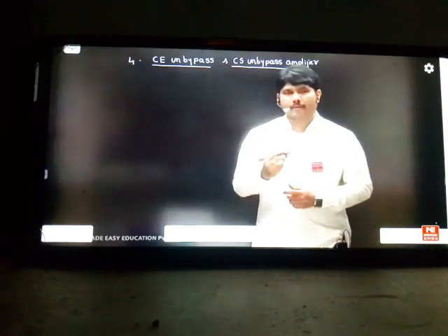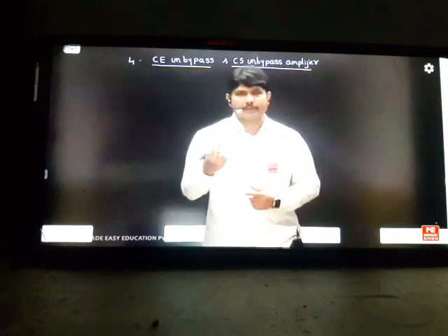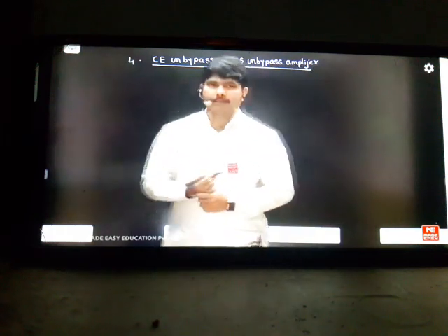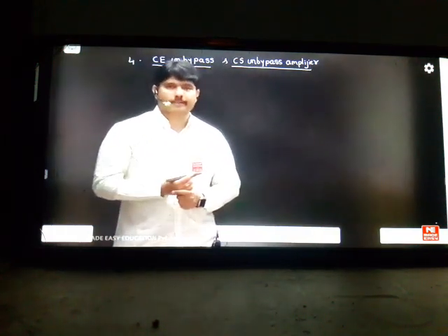Lastly, one more special amplifier is the common emitter unbypassed amplifier. Bypass means there will be no negative feedback, RE will be 0. Unbypassed means we are keeping the feedback in AC analysis. Then what happens to your characteristics? That is the observation. Okay. Let us start.